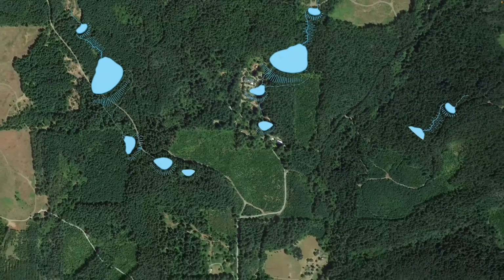If I feel like there is an intact riparian ecosystem with the integrity of a natural waterway, I don't like to take water out of a valley and permanently divert it into a next valley over. It's important to consider as you move water from valley to valley, if you're doing watershed scale earthworks, that you might not want to steal too much water out of any given valley. So a trickle tube is a way to take just a small amount.